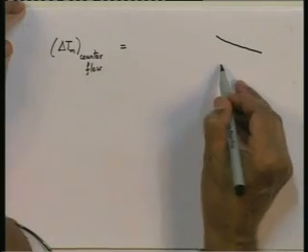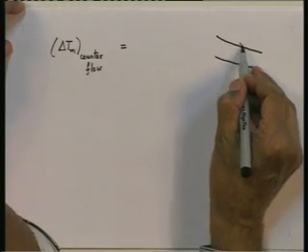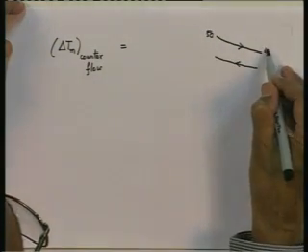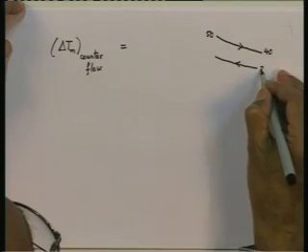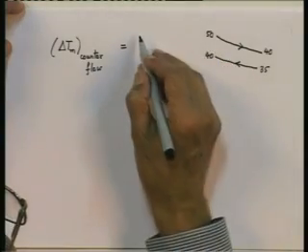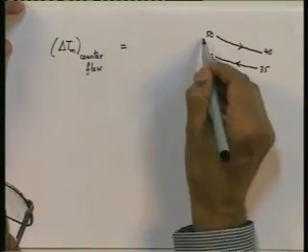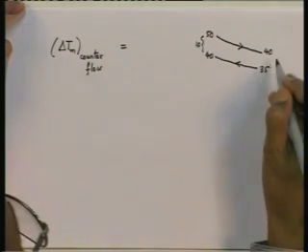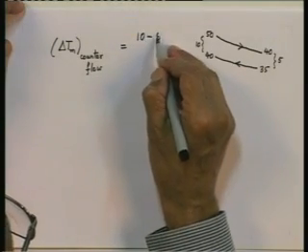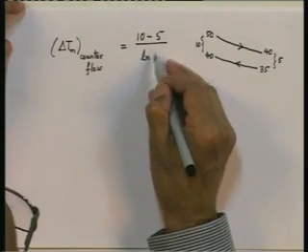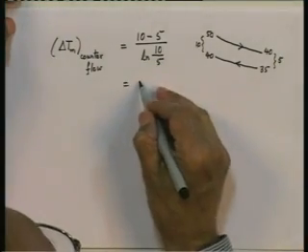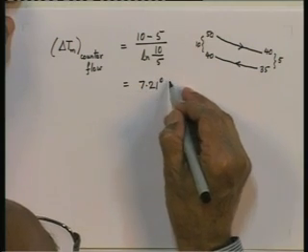Let us draw a sketch as if it is a counterflow situation, starting with 50, going out at 40 on the hot side, cold side entering at 35 and leaving at 40. So, we have delta Ti equal to 10 and delta Te equal to 5. So, we have 10 minus 5 divided by the logarithm of 10 divided by 5, which comes out to be 7.21 degrees centigrade.